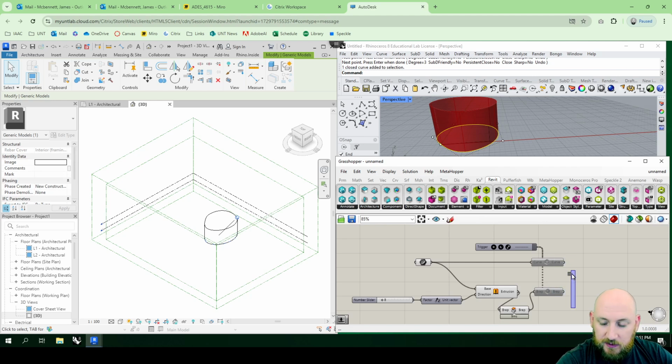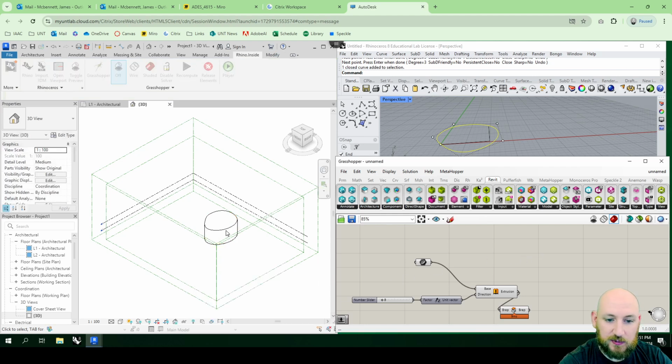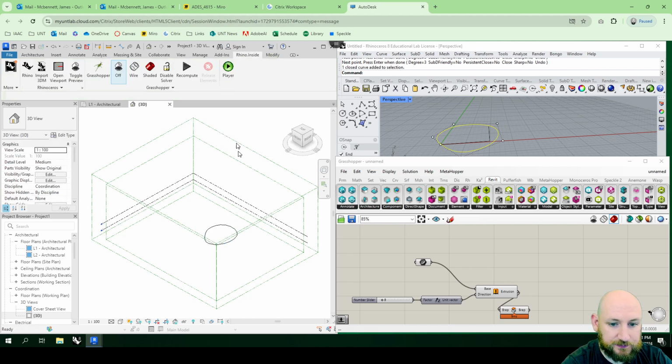One other issue with this workflow is this is an instruction to create geometry. It's not an instruction to delete geometry. So if I was to delete this, it says the link is broken, but it also does not delete it from here. So I need to select this. If it's pinned, which depending on the situation it might be, you would need to unpin it with the shortcut UP, or where my mouse is, this unpin, and then you can delete with either DE or delete.